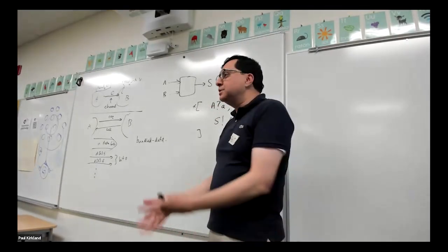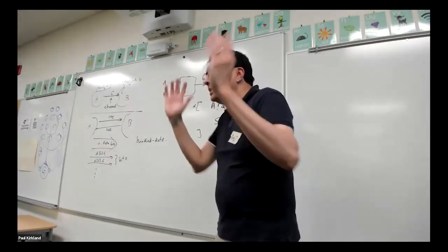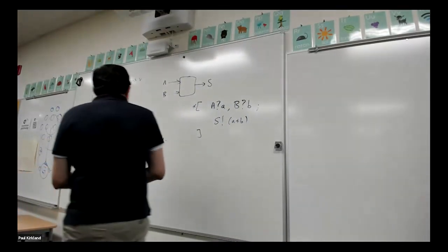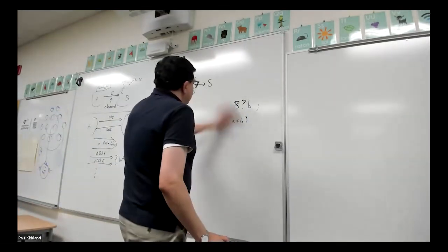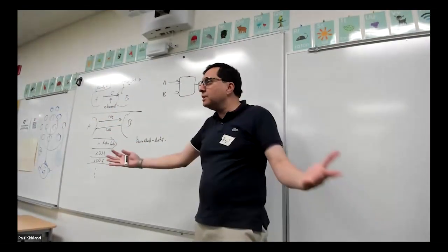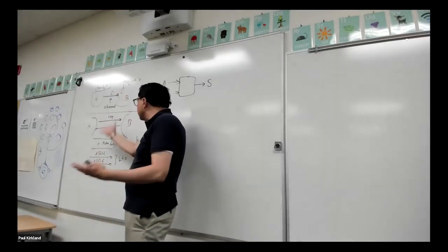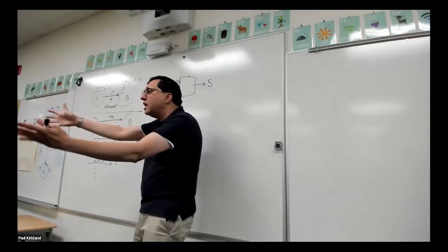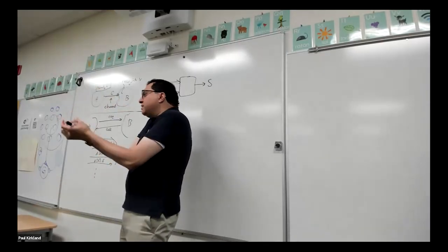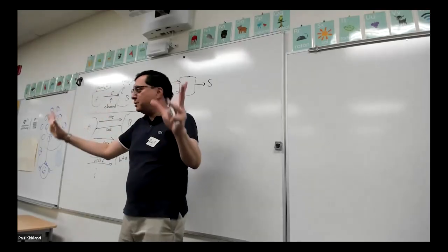So eventually I need to turn this into some circuit that I'm going to implement in CMOS, maybe other technologies. But I mean, I'm a big fan of CMOS. So my starting point is a behavioral description in this message passing programming language. You will pick your protocols for your channels. So that tells you the wires that you need to drive on the interfaces. You'll take your variables and say, okay, I have a 20-bit variable. I convert them all to Boolean variables.